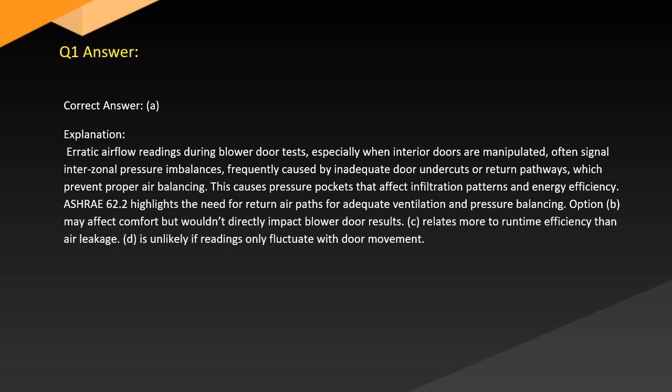This causes pressure pockets that affect infiltration patterns and energy efficiency. ASHRAE 62.2 highlights the need for return air paths for adequate ventilation and pressure balancing. Option B may affect comfort but wouldn't directly impact blower door results. C relates more to runtime efficiency than air leakage. D is unlikely if readings only fluctuate with door movement.